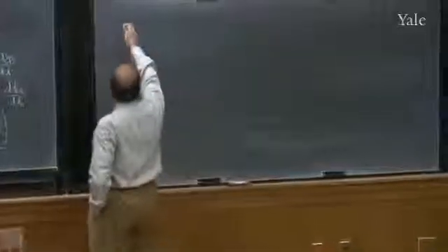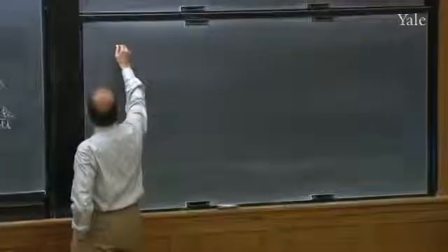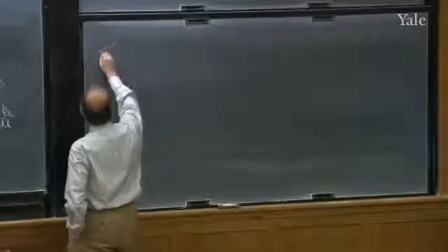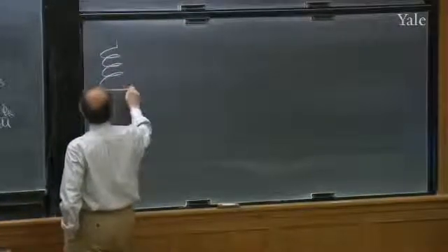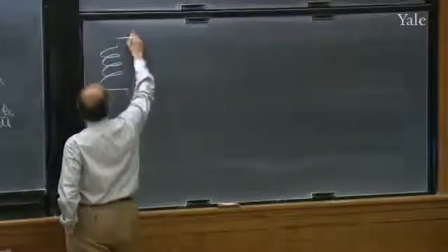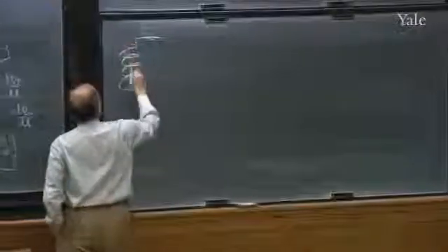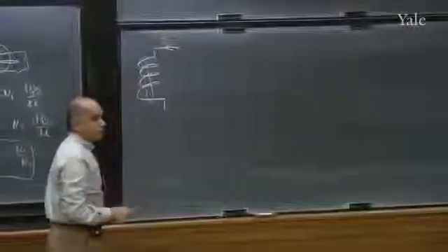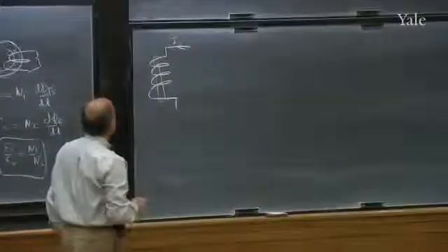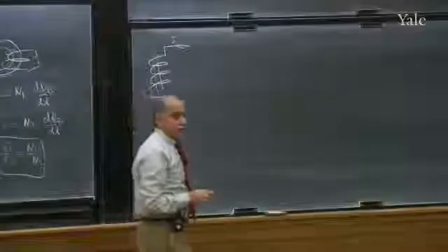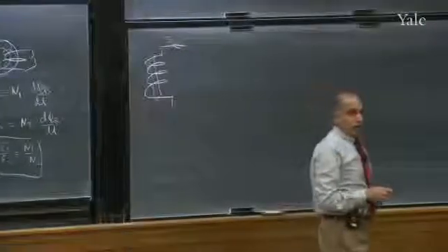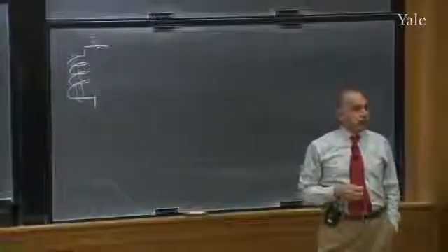All right, so now we are going to do the most important circuit element, which is an inductor, and it looks like this. That's a coil of wire. Say some current is coming in like this. It's wrapped around some solenoid in the form of a solenoid. This wire is a perfect conductor. Therefore, it takes no voltage at all to drive a current through it.